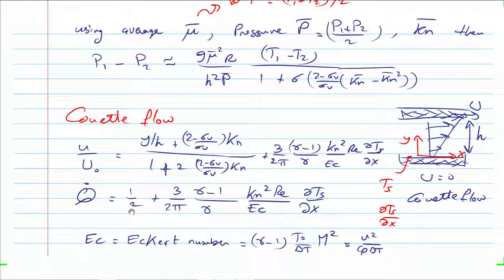Shouldn't that surprise you? This is the velocity profile, and we can clearly see the effect of slip on the velocity profile. But when it comes to the volumetric flow rate, it's half, just like the flow rate that you would get without slip. So the slip at the upper wall and lower wall didn't really affect the flow rate.